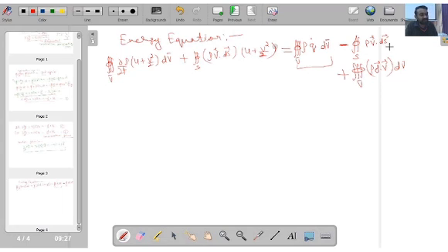Now you might be surprised to know that I have not taken some of the terms, because I am writing the energy equation which is useful for compressible flow analysis. For this analysis, as we are not considering the viscous dissipation and the irreversible effects, the conduction term and viscous forces term I have not considered over here.